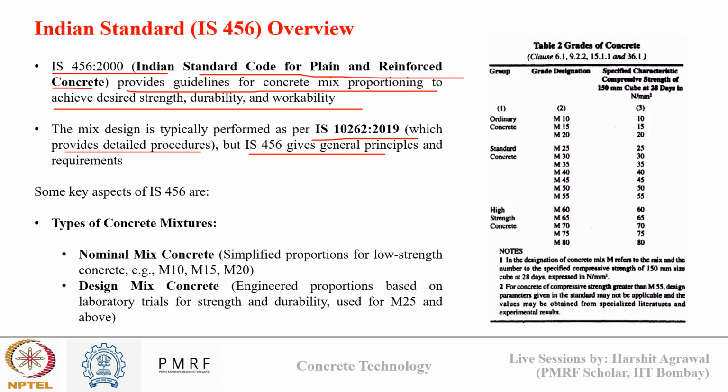Okay, so there are several key points in IS 456 which are related to mixture design. First of them is the type of concrete mixture. So first we'll discuss IS 456 and then we'll discuss IS 10262. So in IS 456, the first key point is the type of concrete mixture. As per Indian standard, concrete mixture has two broad classifications. One is the nominal mixed concrete, and second is the design mixed concrete.